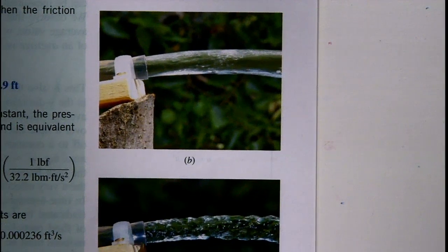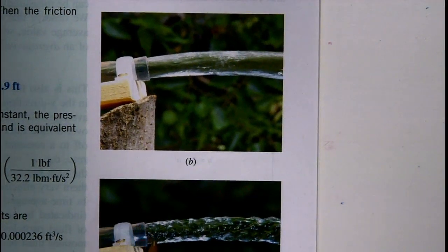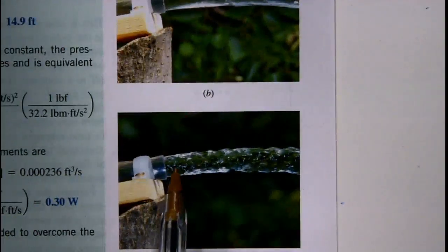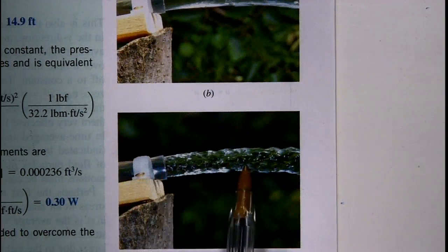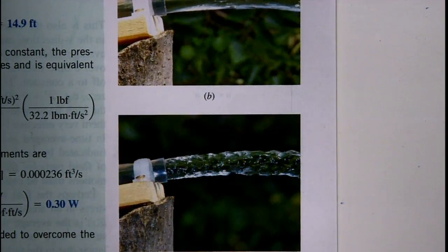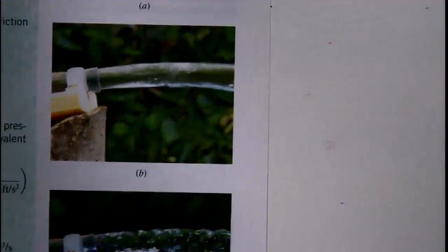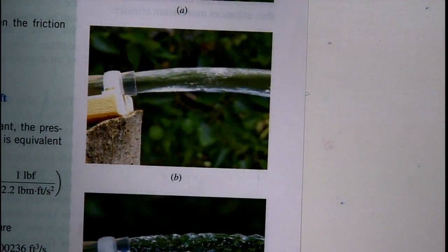See, when the flow exits the pipe, the no-slip condition no longer applies. So the center core slows down and the outer perimeter speeds up. The flow rebalances itself, so to speak. It's kind of intriguing. I don't know if that's important. I wouldn't worry about the fact that the flow slows up in the center line and speeds up around the perimeter. Only in the areas of, say, atomization would you worry about this.